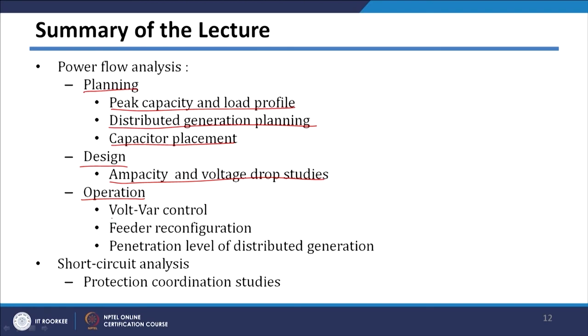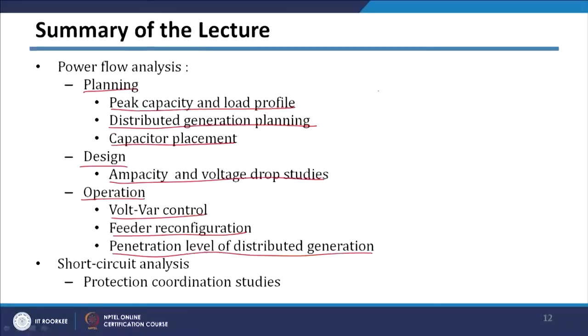And then in operation, volt var control, feeder reconfiguration and penetration level of distributed generation. And we have discussed how load flow studies are an integral part of these studies, because all these studies are based on load flow calculation, that is, calculation of voltages all over the distribution system as well as line flows in the distribution system. These various studies can be carried out.